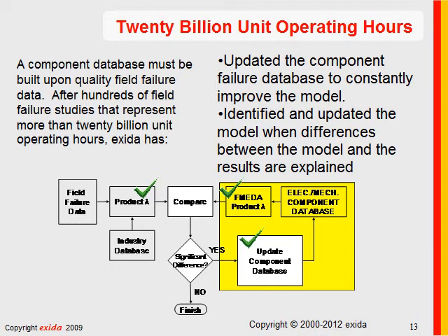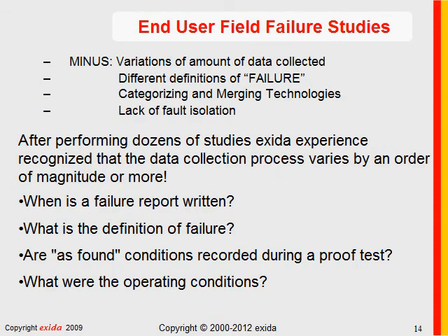However, FMEDA predicts a product failure rate, not what I call site-specific failure rates. In other words, maintenance-induced failures, and we'll talk a little bit about that later.